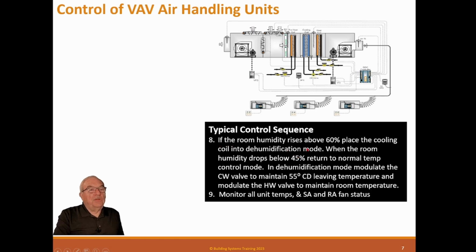If the room humidity rises, okay, this air handler has a cooling coil and a heating coil, and it's got some reheat coils downstream. So we can dehumidify that. You can also dehumidify if one has heaters on all boxes, then you can use those for reheat. The only warning is those reheat coils need to be large enough to do the reheat when you're in dehumidification